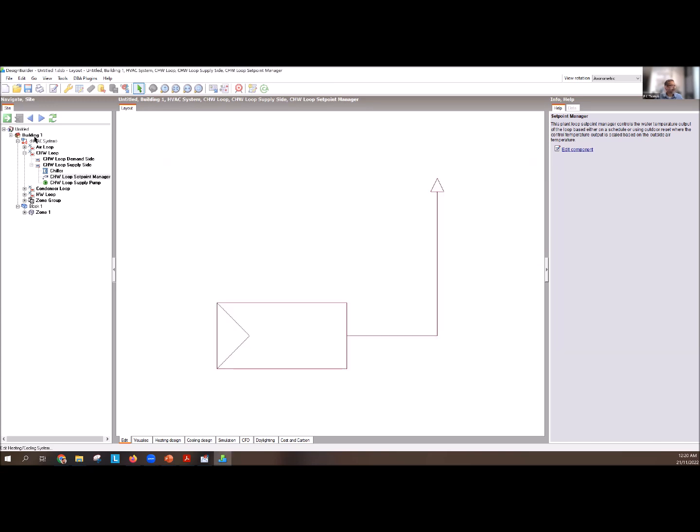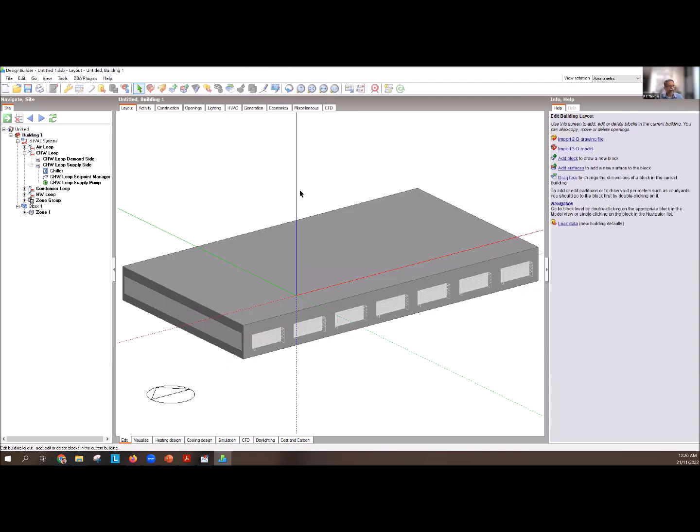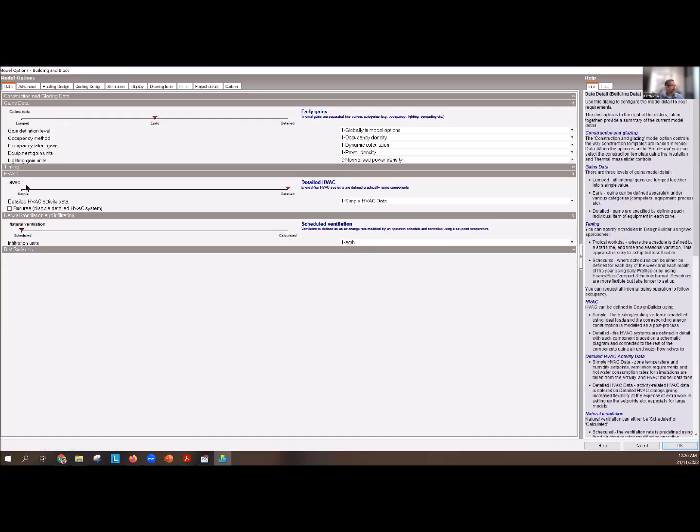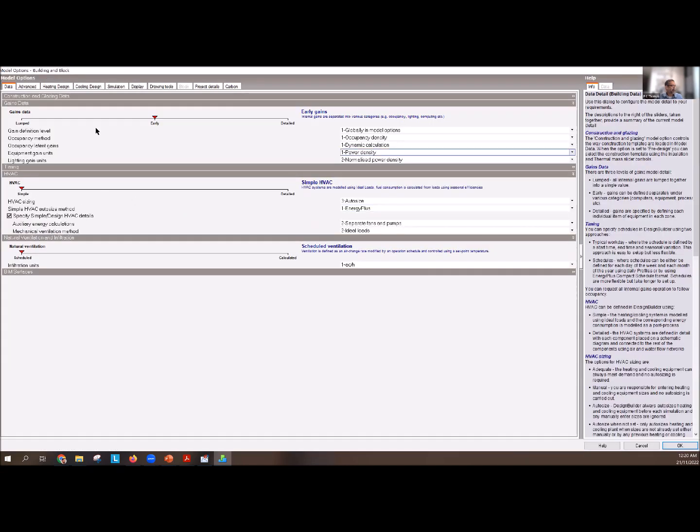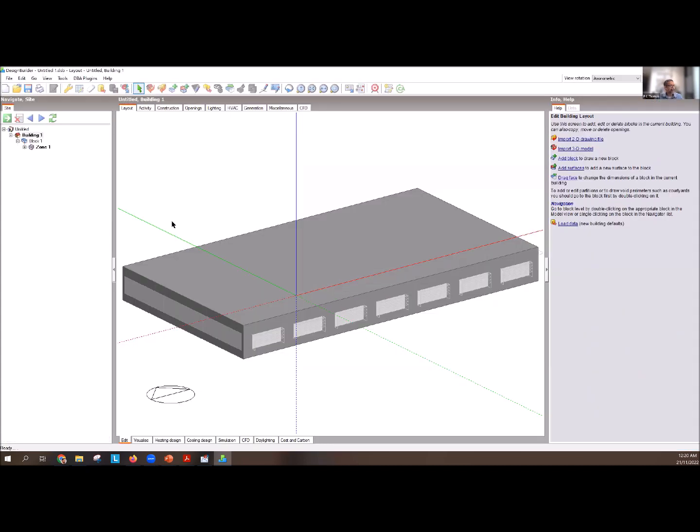If you know your air conditioning, it's quite comprehensive to do. But in the beginning, to fix up your facade and building envelope, to just see how well it performs compared to a base case, use the simple air conditioning system. Look at those district heating and cooling loads. They give you the best outcomes.